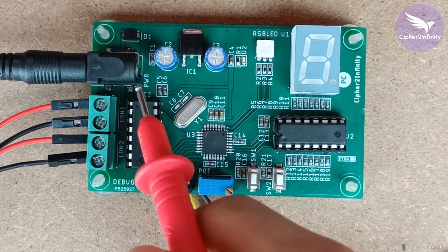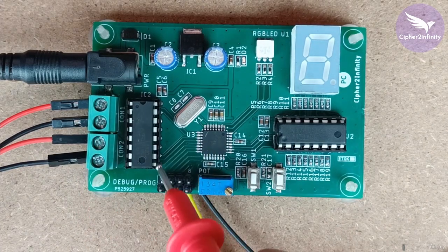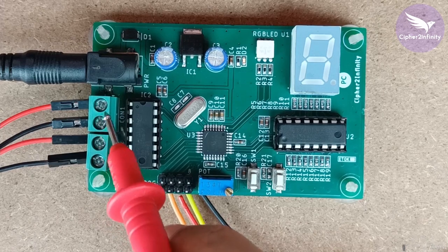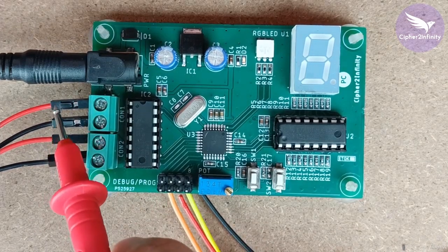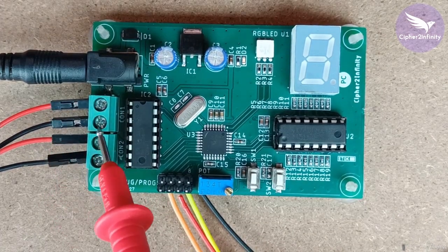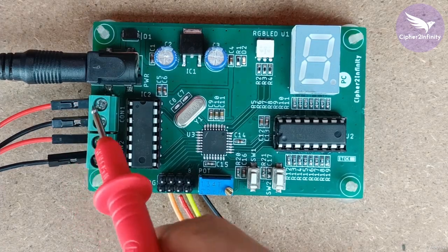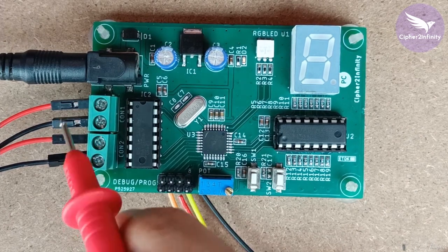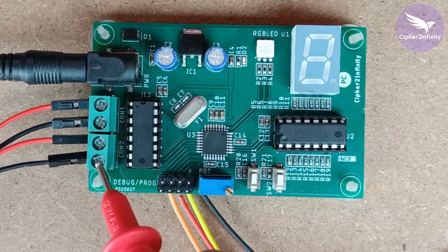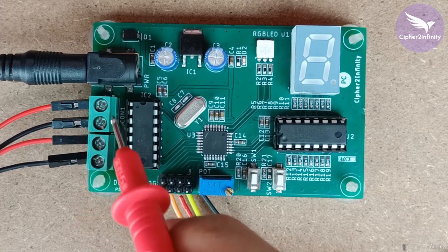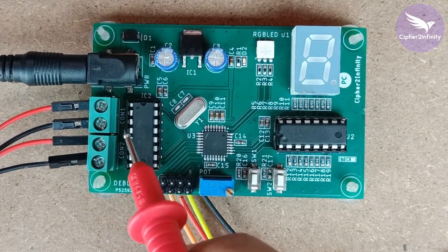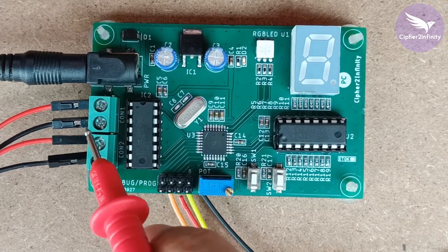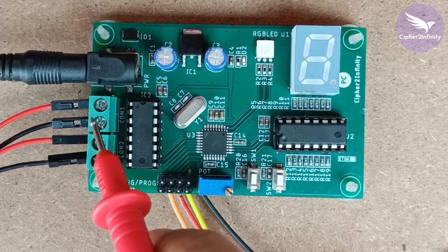But let's say there is a problem with the motor driver section. Then the first thing you have to check is contacts. Check whether the pins you have connected to these terminals have tight screws. Make sure there is no loose contact here. Once you have verified that, check again whether the motors are rotating or not.